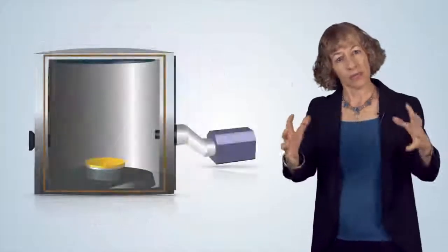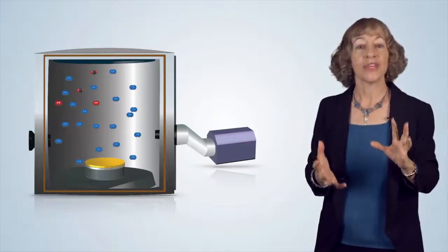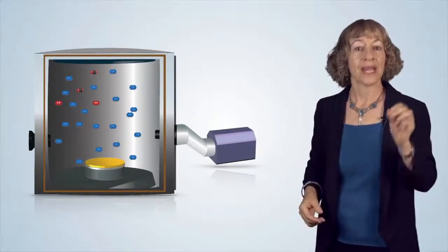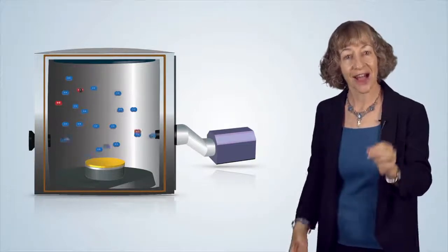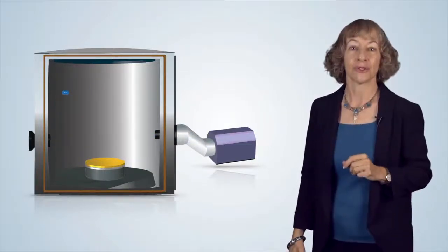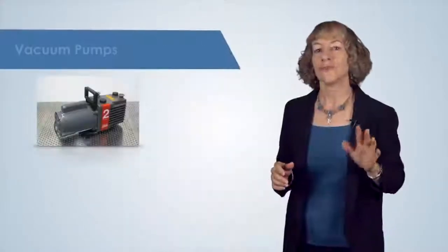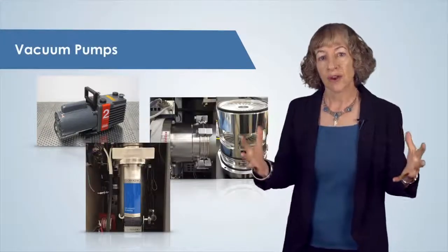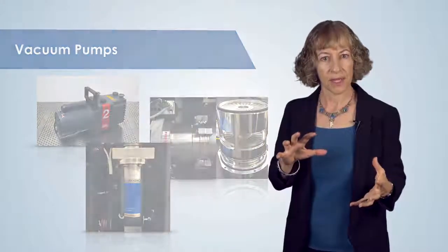A vacuum chamber is designed for high-yield, thin film deposition, where more than 99.9999% of the air is removed. Another way to think of just how empty a vacuum chamber is: for every 100 million air molecules present in the chamber when open to room air, we remove all but 1. How do we do this? Through the use of vacuum pumps that remove the air from a sealed vacuum chamber. Let's take a look at a vacuum chamber at Duke.